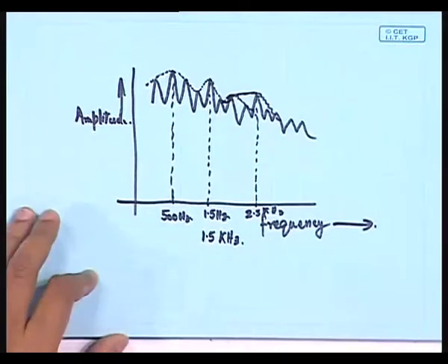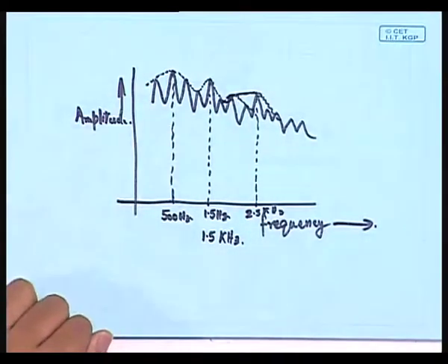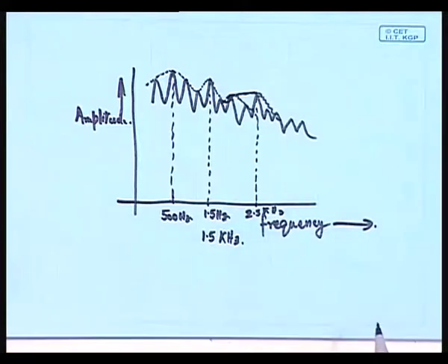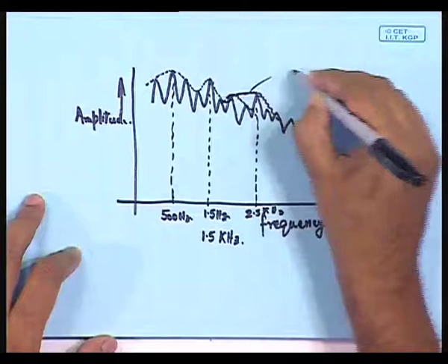So the amplitude spectrum would be something like this, whereas if you consider the excitation model directly, your excitation signal has a very flat spectrum, but after pulse shaping through the vocal tract, because as I have been telling you again and again, the vocal tract acts as a filter, and very precisely a time varying filter, this would give rise to a spectrum like this.